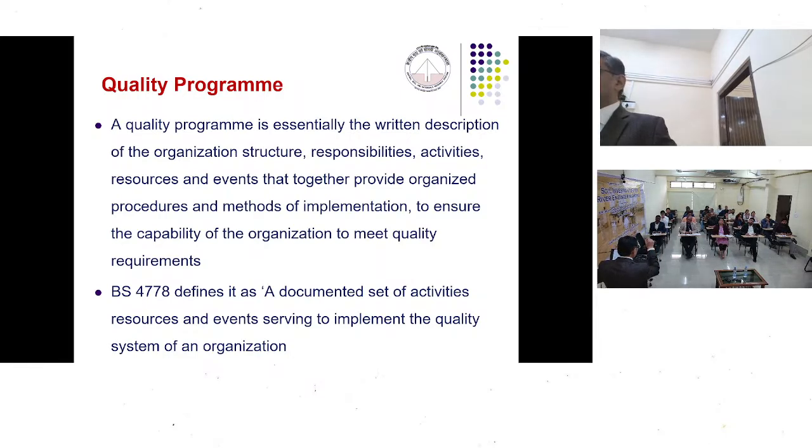You look at the in situ density values recorded in the field, and mechanically you say that at these particular locations the required density has not been achieved, and out of maybe 100 instances, 50 instances are wrong, or 20, or 10 instances are wrong.